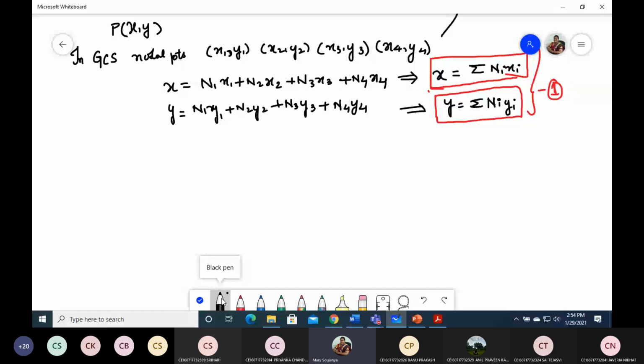And the convergence criteria of the displacement model we are taking also has to be satisfied. All these things we have learned till now for the triangular element and rectangular element are taken as they are in the isoparametric concept. Just understand that the shape functions we used till now to define deflection are also used to define geometry in the isoparametric concept.